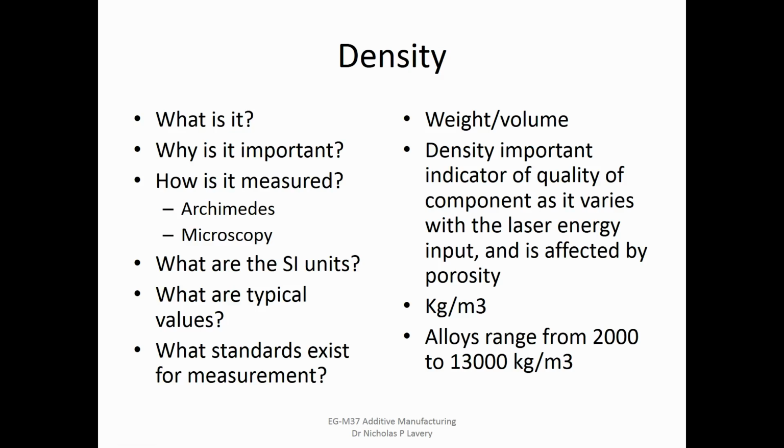Density. Okay, when we talk about density, really what I'm trying to get at is porosity. There are various ways of measuring density. We can use good old Archimedes, dip it into water, and compare that to the density of the water, and possibly make some corrections for the density of air, and it will come up with a value of density.